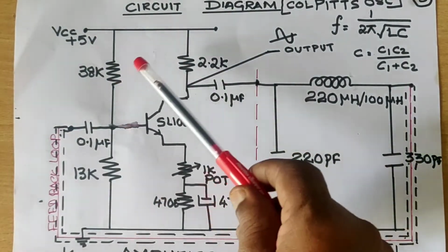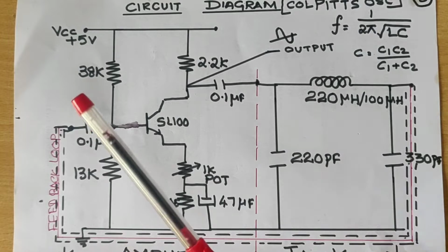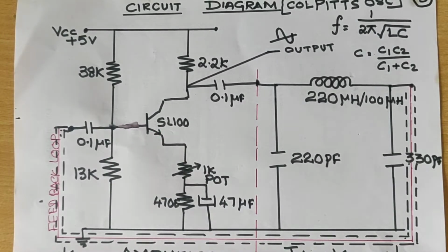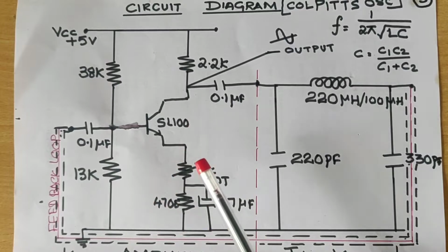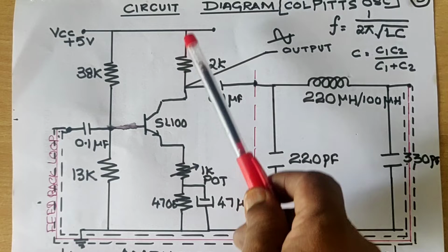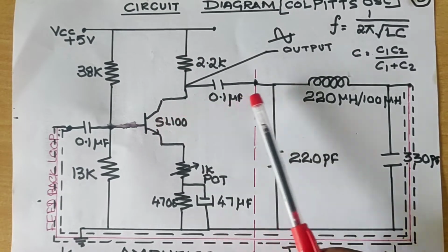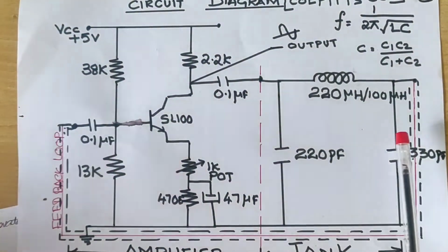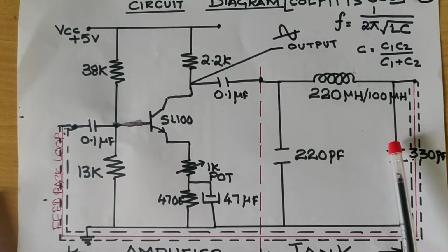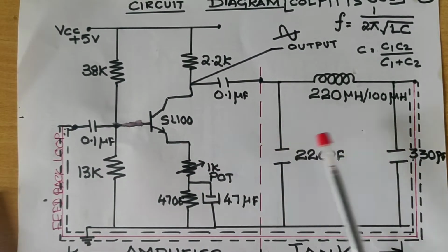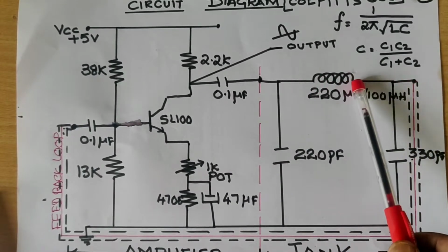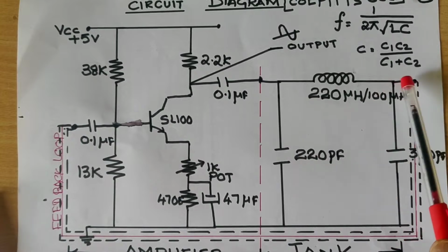When the power supply is given to the circuit, the transistor will turn on by a small noise voltage as a biasing voltage. This causes the collector current to grow up, and thereby capacitors C1 and C2 start charging. Once these are fully charged, they start to discharge through an inductor, setting up damped oscillations.